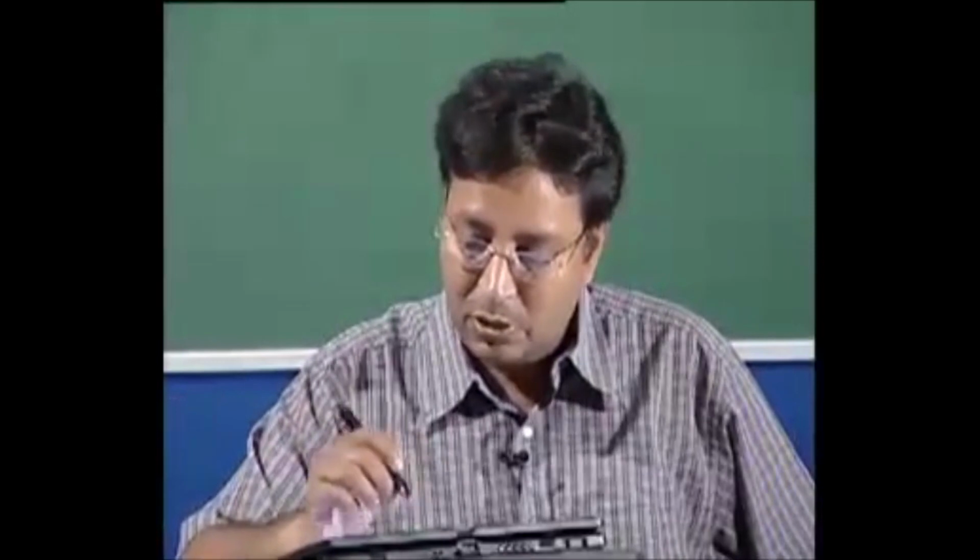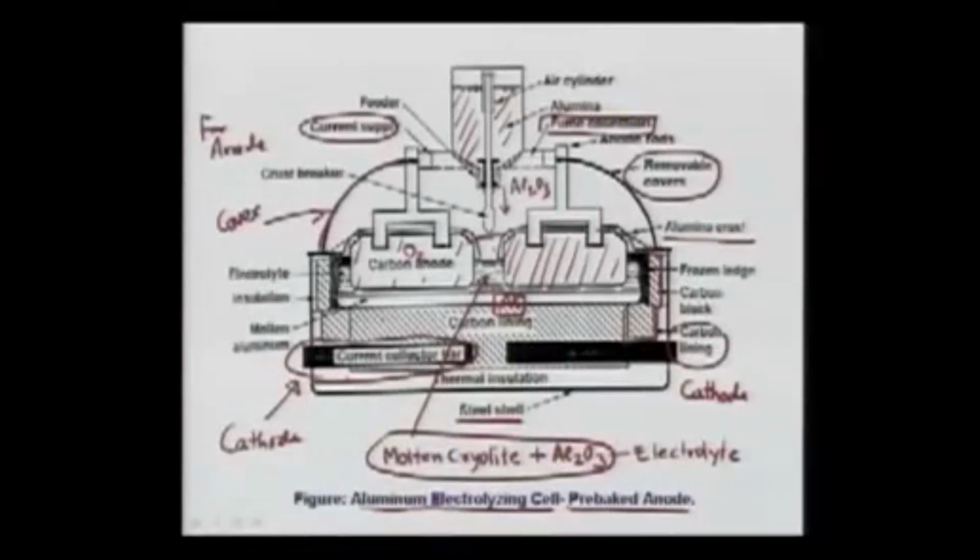So we'll talk about the emissions in a moment, but here what you have to remember is, this is the electrolysis process that is going on and the anode is being consumed. And the anode, which is this thing, is already pre-baked. It is in solid form. Something baked, you go to the bakery and you find solid things which are baked, like a biscuit, it's not a paste.